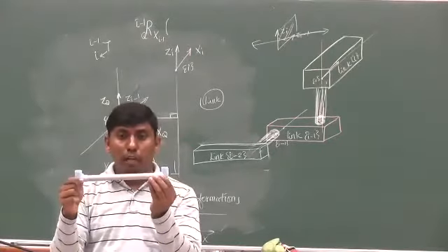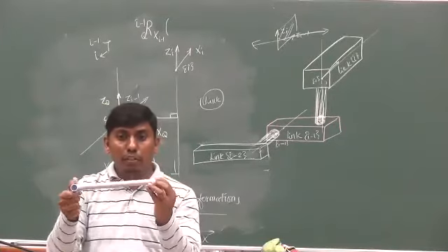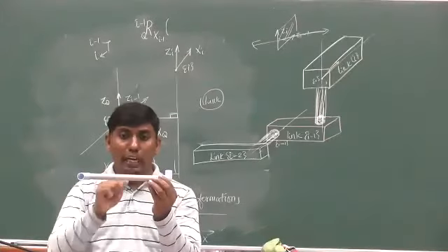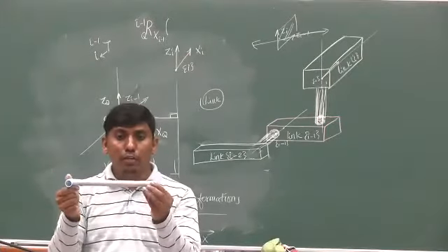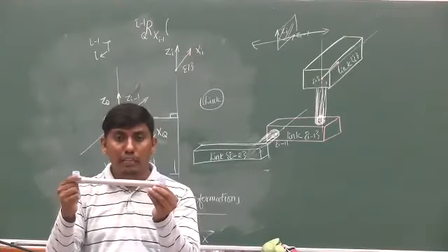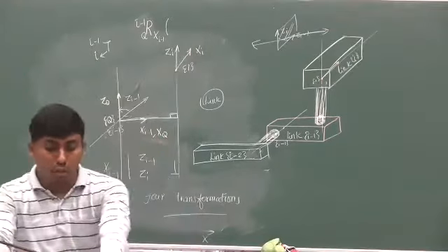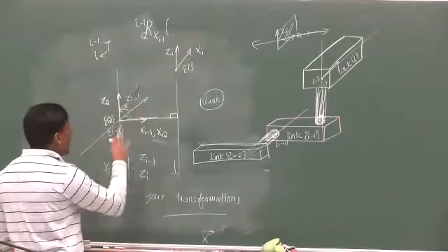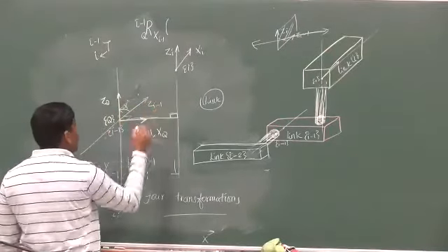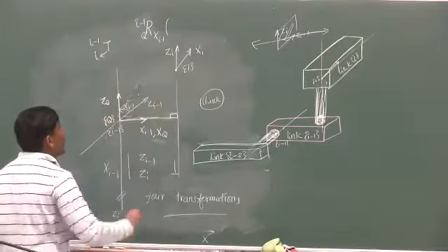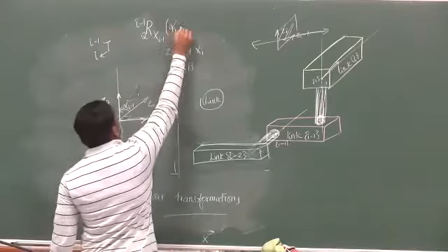Now what I'm seeing, these two are twisted like this, right? One is towards you and one is vertically up. So now what angle you are doing? You are rotating about this x and you are making it this. Right? So that is what you are calling twist angle. So now this angle is called alpha, and since we rotated about xi minus 1, I call it alpha i minus 1. So this is the first operation we have done.